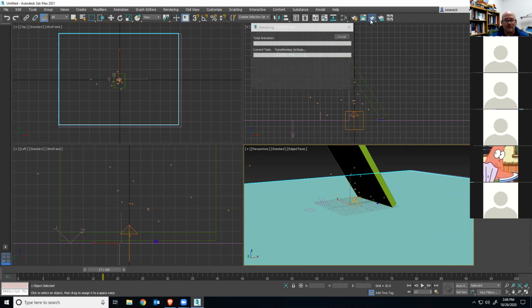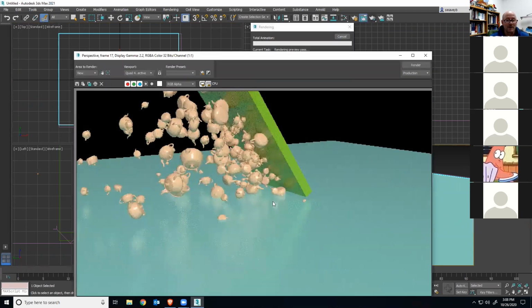So at least now, when I render it, it's way too bouncy anyway, but I should see a little bit more. Now I get some light bouncing off the floor, so now I can see the underside of the box. There it goes. You might also notice this isn't perfect because some of the teapots look like they're in the floor, and indeed they are. It's really just using the base point, the pivot point of each of these particles, to see when they're bouncing. That's usually not that big of a deal because the particles are moving pretty quickly, you can't really tell.